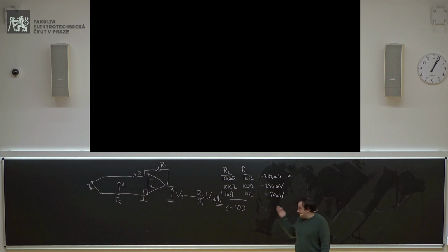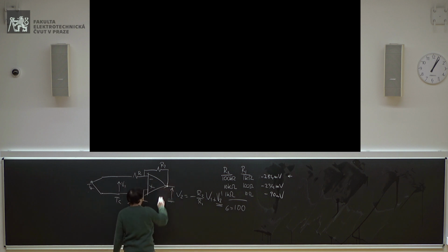True? Well, definitely, if you have smaller resistances, you have bigger currents. But let's try to calculate them. So again, let's take the two extreme cases. How do you calculate the current which is generated by the operational amplifier? Well, here you have an output voltage which is basically exposed to infinite input impedance because you have a voltmeter, and the voltmeter doesn't absorb any current, okay? So the current that you observe getting out is the current which goes to R2.